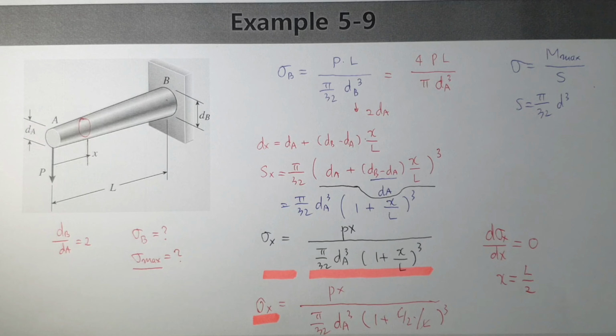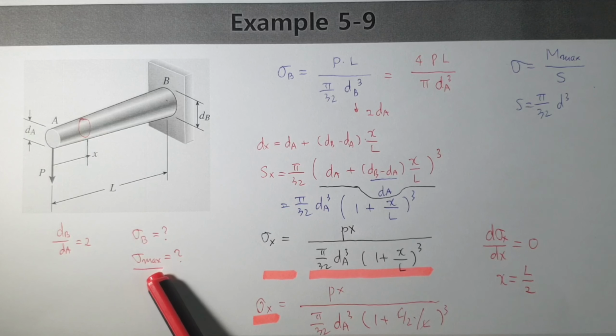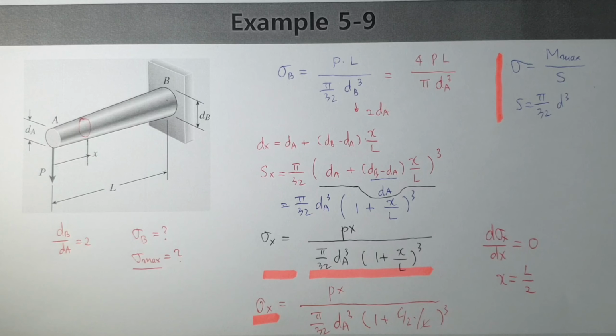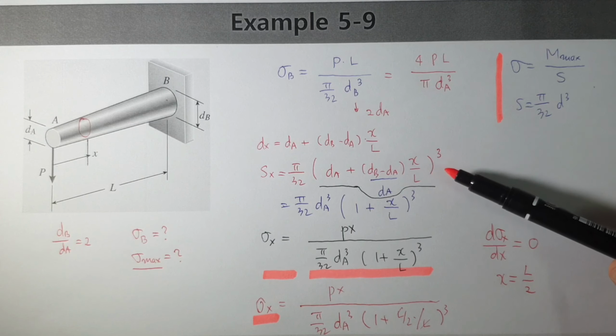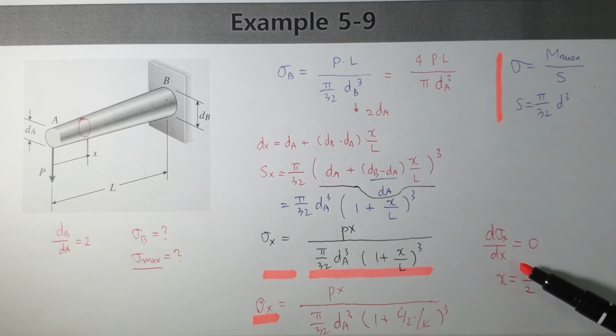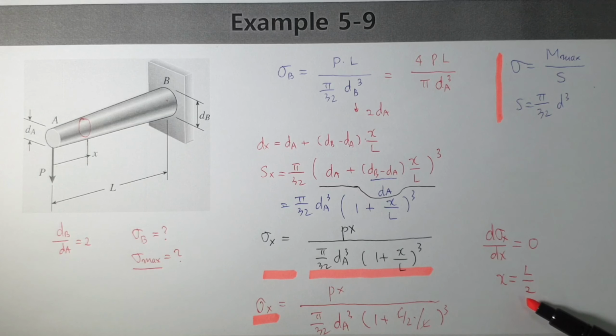Okay, we've seen here the maximum sigma value and maximum bending stress at this point. We also applied this kind of relationship. We start with the diameter and section modulus. Let's calculate like this one. We derived sigma x and took the derivative, finally getting the solution where the maximum value happens. Then if we substitute it there, finally we can get the sigma x value like this one.